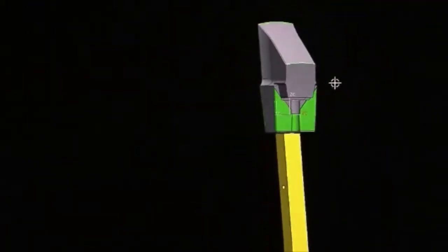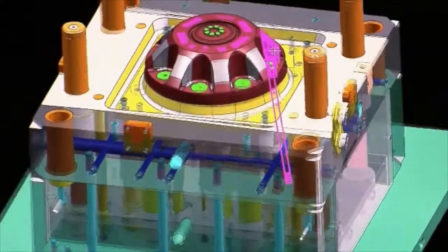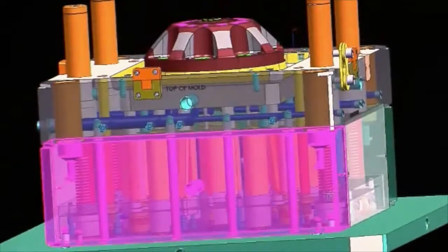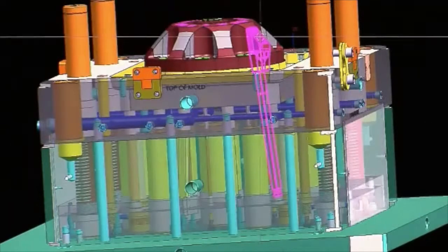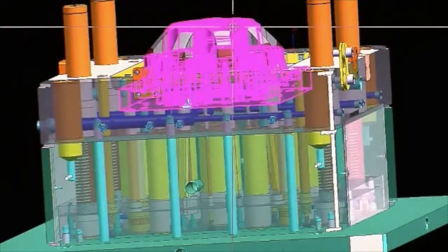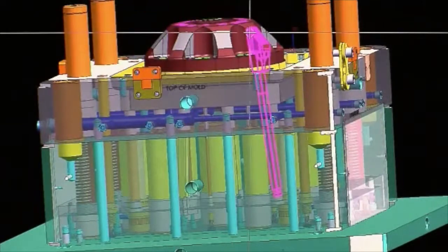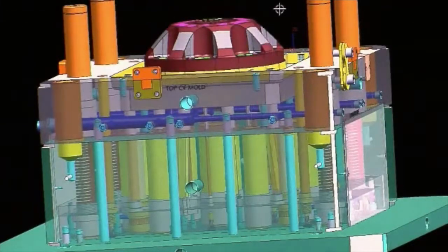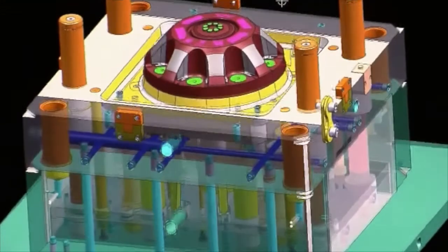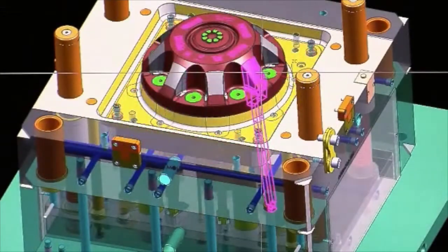That is a Mold Wizard component. We dropped that in. It automatically knew to hook into the ejector plates down here. All we did was put the part area on it by wavelinking in the part geometry into the lifter file and then trimming it off. And if we ever update that part, that lifter will update automatically.